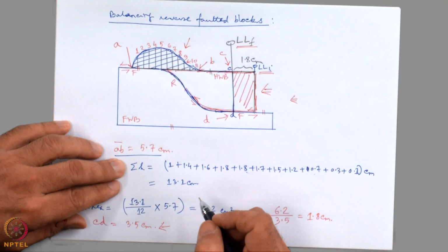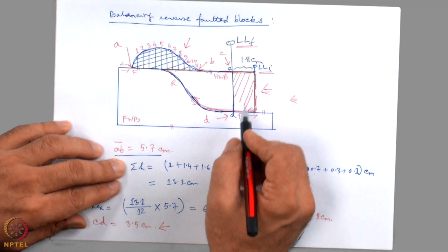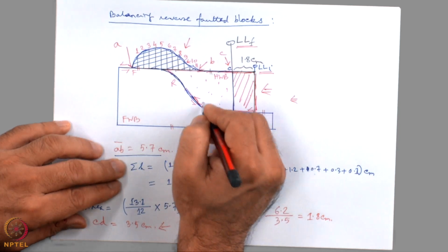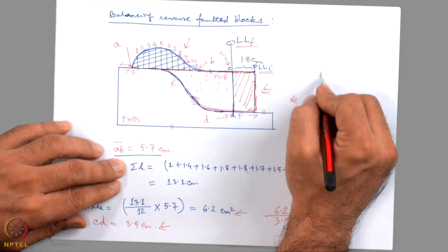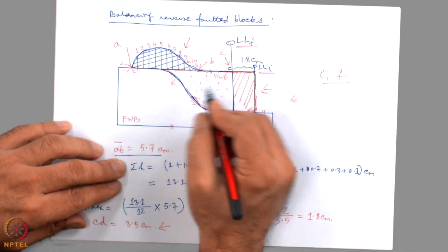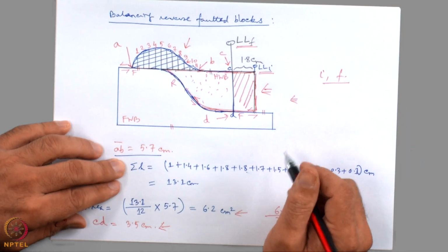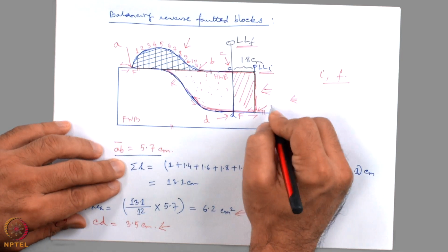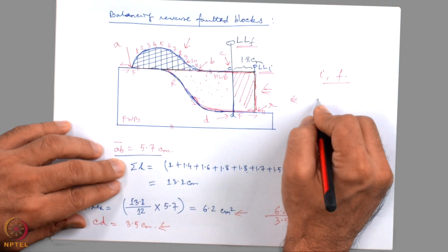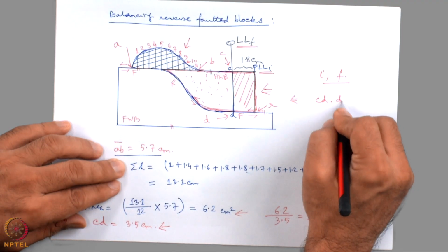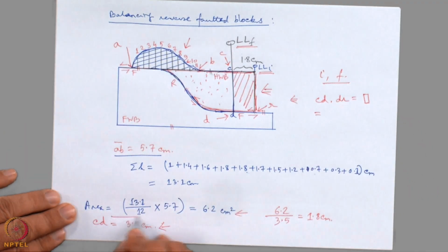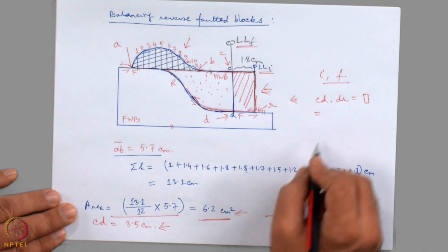We have assumed no area has been lost and no area has been gained overall. Therefore, the area loss here is equal to the area gain there. What about this area? This area is a common area in the initial and the final condition. Therefore, we did not bring it into the calculation. Note that this length CD multiplied by, say this point is R, CD multiplied by dr is the area of the rectangle, and that is equal to the area calculated here.